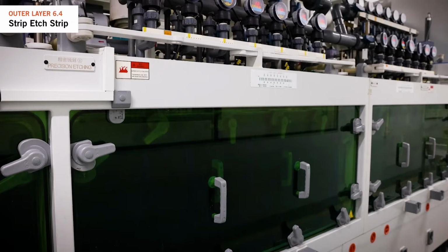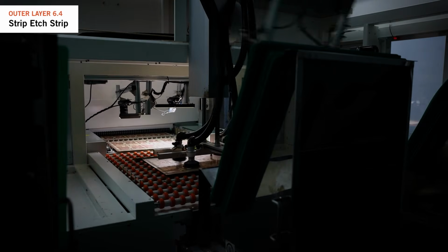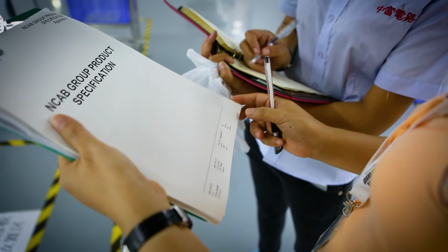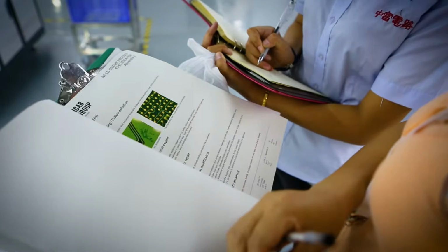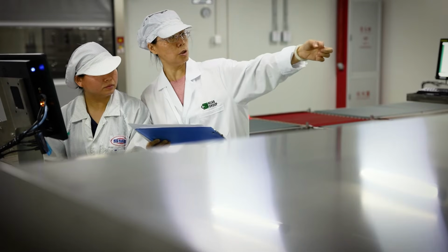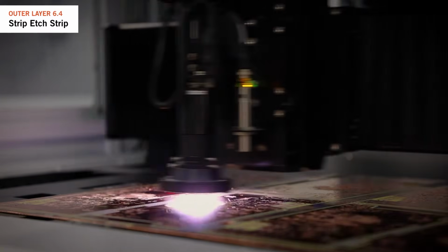During etching, tracks can sometimes be etched in areas they shouldn't be. However, based on our own demands, we don't permit the repair or welding of open circuits as it could impact reliability. To ensure quality in this step, we check with the factory to understand how they inspect the physical PCB track widths as they come off the line.